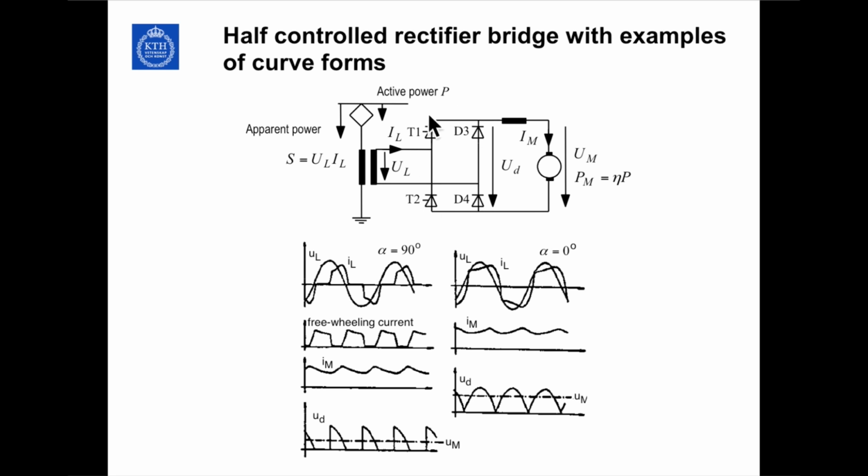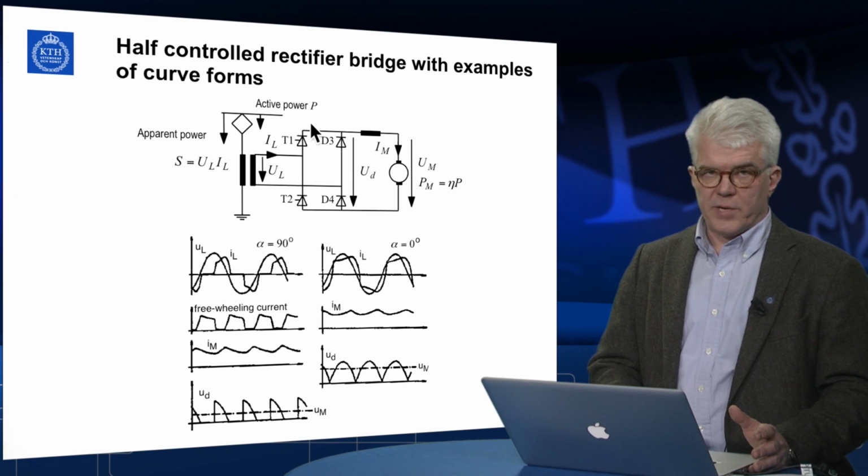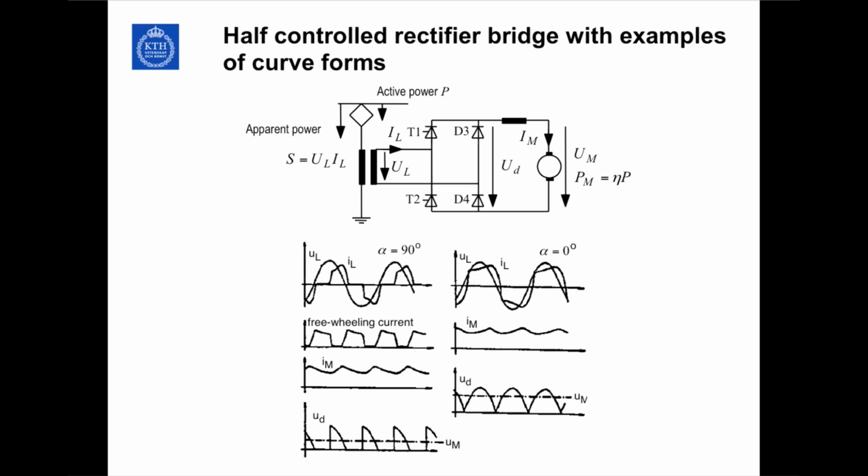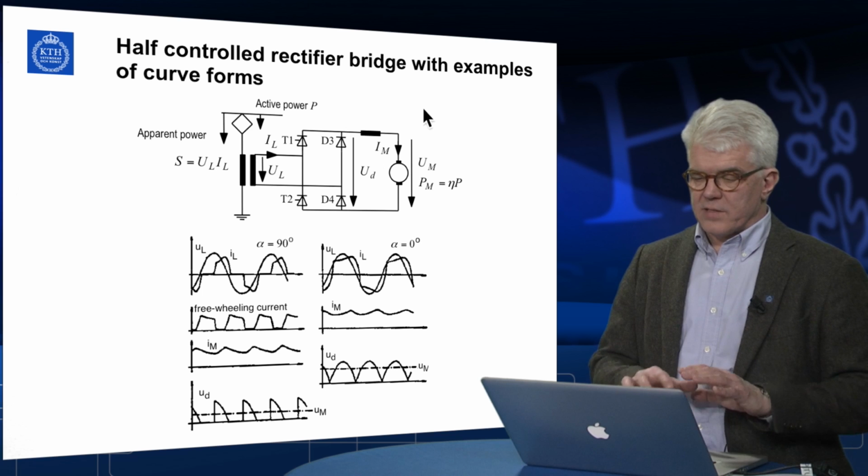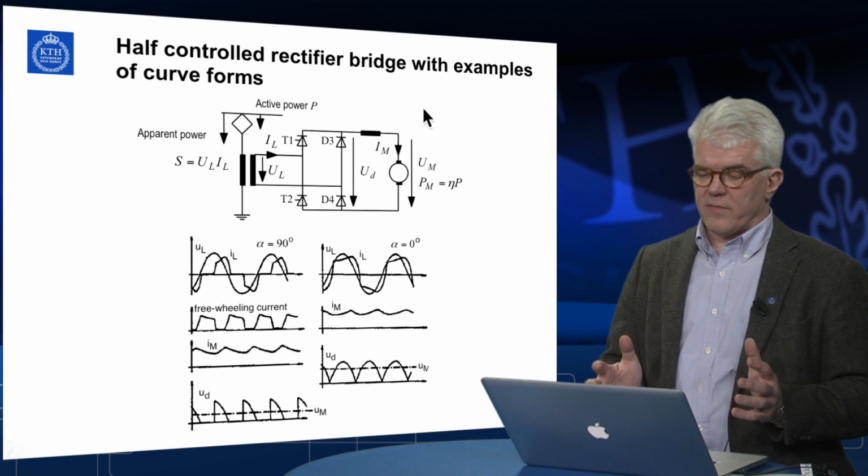Later on, half-controlled thyristor bridge was the common choice for this kind of drive and application. That is, we have diodes in one of the phase legs, and we have thyristors in the other phase leg, as described in Chapter 3 of the textbook. So this is connected to a transformer on the second, connected to the line. We have the pantograph. We have the DC motor. This constitutes the complete drive of a DC traction train.